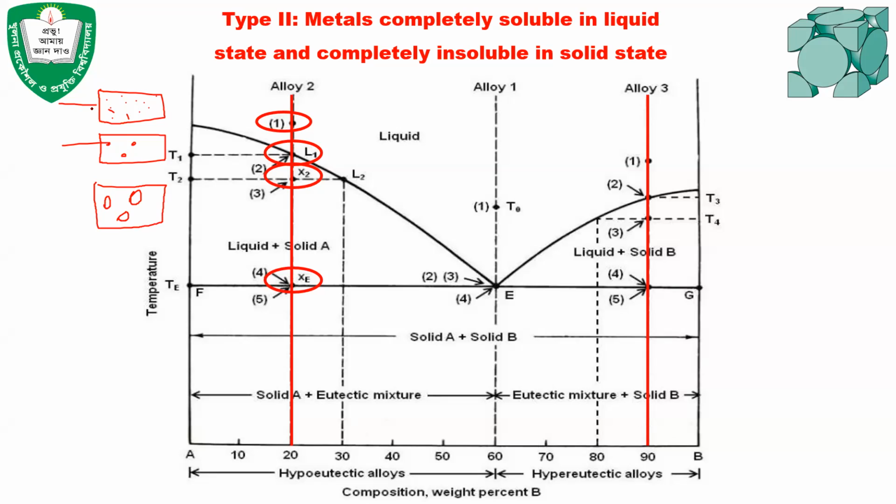If you want to show the chemical composition, it will be 80-20. In this case the composition will be very close, so there will be a very small amount of solid. The solid chemical composition is 100% A, and the liquid composition we can read from very close to this, so let's say 21B, for example.